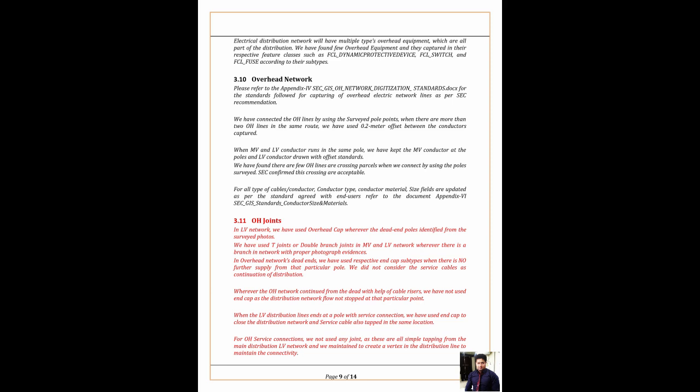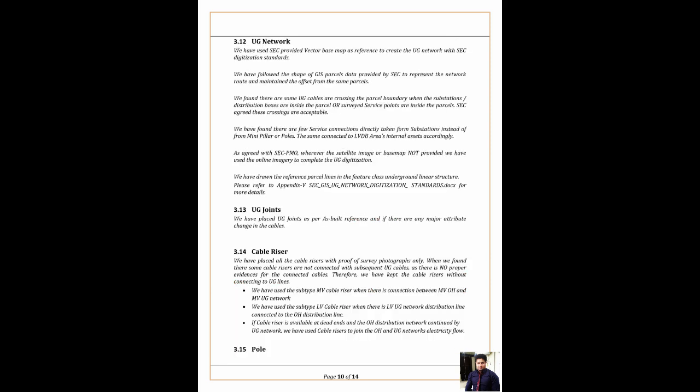When the LV distribution line ends at a pole with a service connection, we have used an end cap too, to close the distribution network, and the service cable is also tapped in the same location. For our service connections, we did not use any joint as these are all simple tappings from the main distribution LV network, and we maintained a vertex in the distribution line to maintain the connectivity.